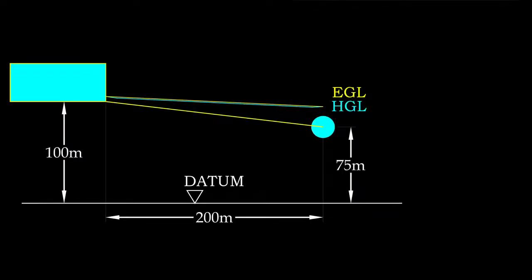The difference between HGL and EGL is negligible, since the velocity head is too small compared to piezometric head. In water reticulation design, hydraulic grade and pressure head at the destination nodes are of concern to ensure the water supply satisfies consumers' daily usage and firefighting requirements.